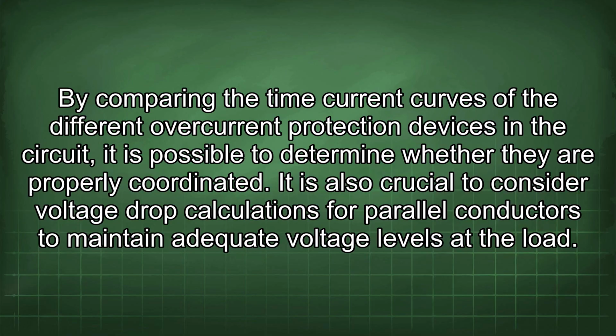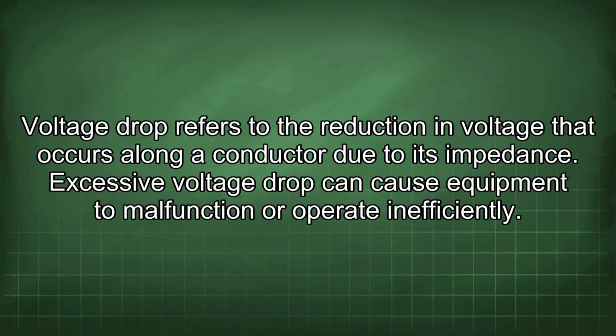It is also crucial to consider voltage drop calculations for parallel conductors to maintain adequate voltage levels at the load. Voltage drop refers to the reduction in voltage that occurs along a conductor due to its impedance.